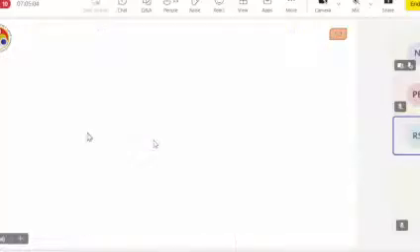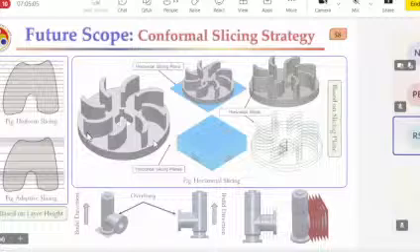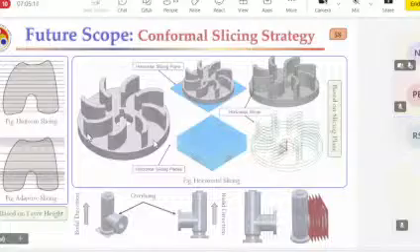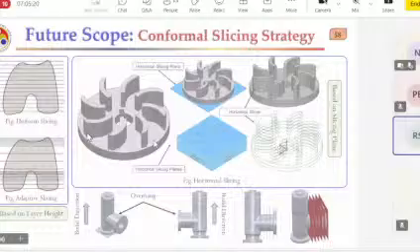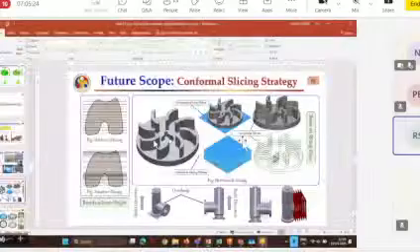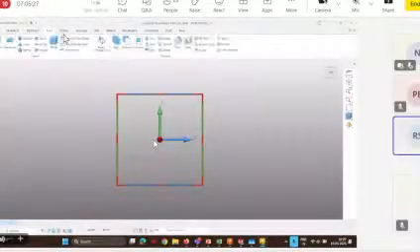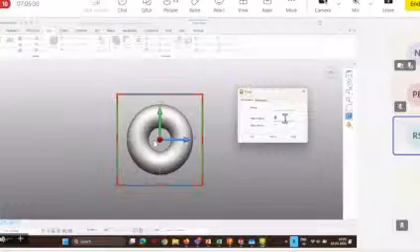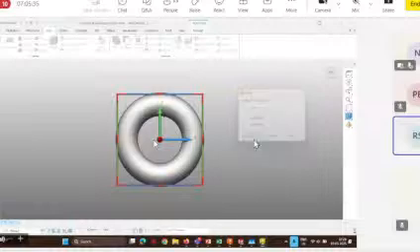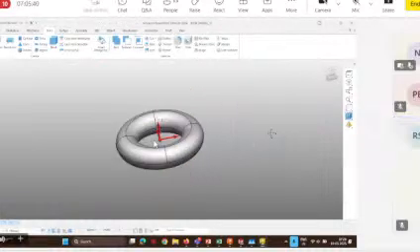So I will just show you how this actually works with the help of this robotic arm. First we'll create the work plane at the zero. Then we can create the cone again. This time we'll keep it a bit smaller, maybe 30, and 10 is fine.